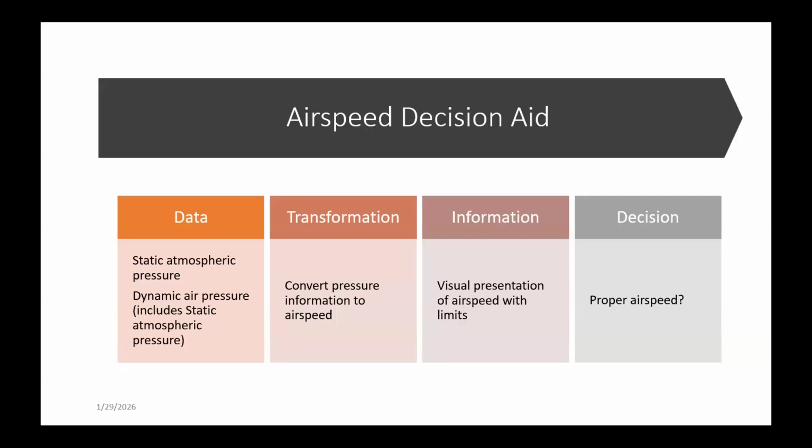All right, so now airspeed decision aid. Again, we're looking at this thing. Can I tell? Do I have to use the instrument? Well, if I'm at 12 or 14 or 17.5, probably. I get down low and I'm in the round out at the bottom of the pattern or bottom of the approach. I'm probably watching a whole lot of things and only slightly looking at the airspeed indicator.